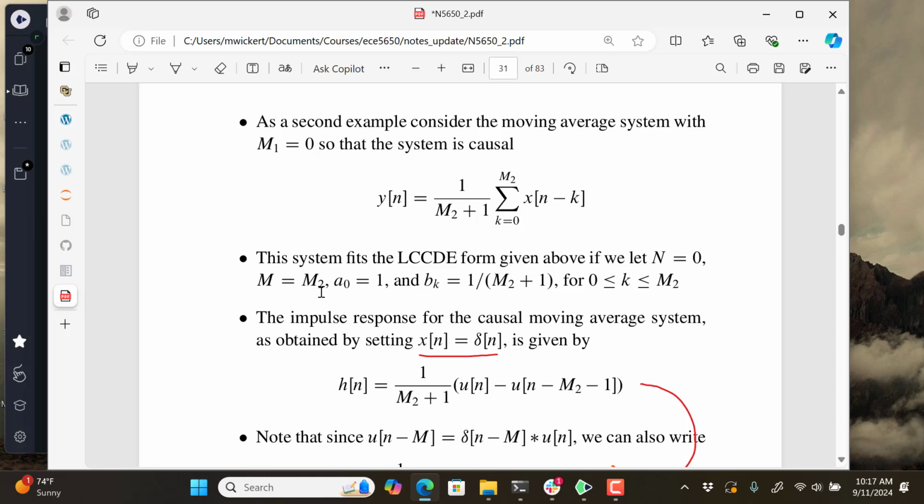I'm trying to get at the idea that looking at different topologies can be more efficient from an implementation standpoint. Less real estate in an FPGA, fewer clock cycles in a programmable DSP microcontroller to get some output. You have to have more storage memory in one versus the other. There are other trade-offs, but those are all things that we like to deal with when we're coming up with a design.